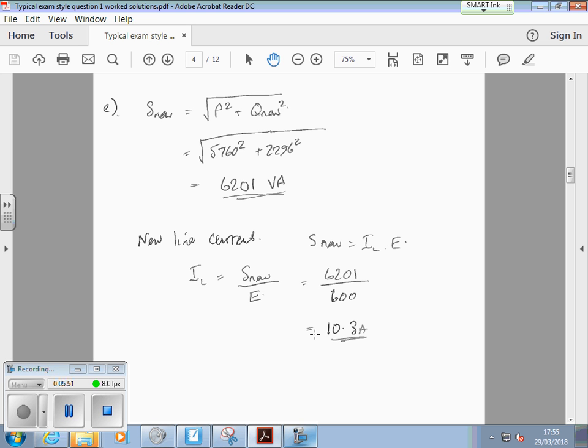And there's that caveat at the bottom that in the actual exam, there might typically be formal marks awarded to use your knowledge to explain the benefits of power factor correction on that system. I could put that in any of the questions that involve power factor correction if I choose to. So that's about you knowing that it reduces the current, so you can use smaller cables and there's less power loss, that kind of thing. Alright, so we're okay with question 1.